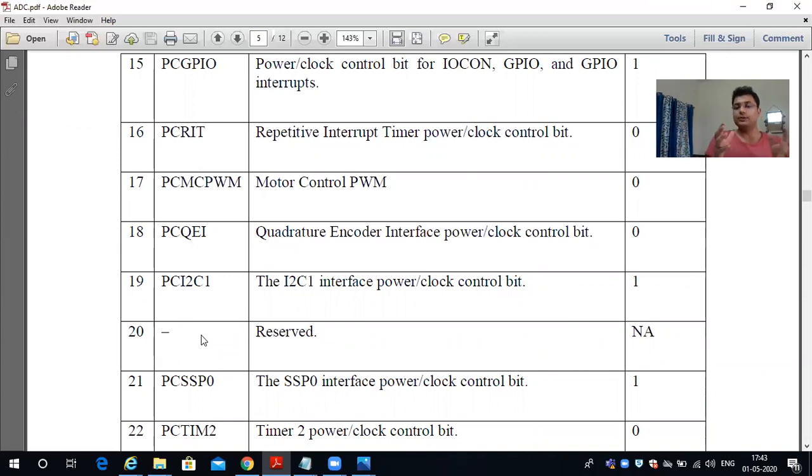So in what order will they sync it? Peripherals are not as fast as the main clock, as the main device. The main device clock works on a higher frequency, but the peripheral device can't work on such a high frequency. So in that situation, they have to slightly adjust their clock. To configure this adjustment, there are PCLK select registers, and there are 4 options.